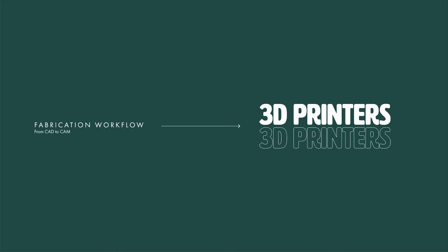Okay, so that's all for our video on 3D printing fabrication workflow. Remember to pay special attention to the resolution of your model that you desire, the angles of overhangs that you have inside your model, where the structure is going to go, and how to optimize your part for the best possible outcome when it comes back from the fabricator. As always, if you have any questions, please feel free to ask myself or any of your tutors, all of whom have plenty of experience with 3D digital fabrication.